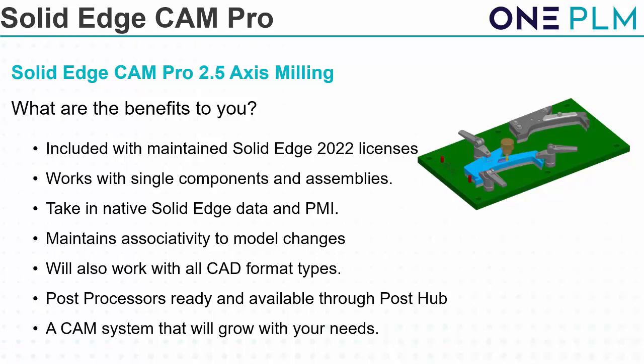So what are you getting within the software and the benefits of having this? Well, it's a package that will work with single components. It'll also work with an assembly of components as well. You'll be able to take in the Solid Edge data and the PMI, so technology built into that, threading data, etc. within the file will be transferred through into the CAM environment and can be used. It will also maintain associativity to any model changes, so making revisions very seamless and straightforward, working between Solid Edge and Cam Pro.